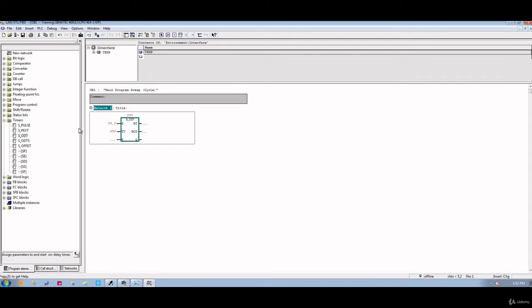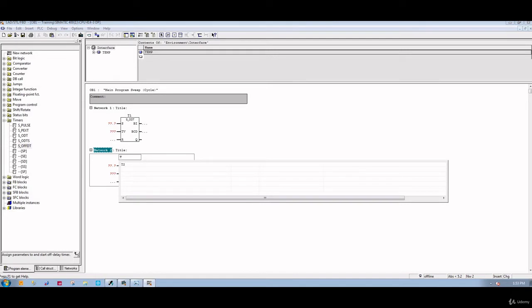We'll try to sample two timers, one called SODT and another one called S_OFFDT. We'll see what's the difference. First, this is the SODT. Let's name that timer. To name a timer, we need to assign a tag name for it. Any tag name for a timer starts with the letter T. So let's name that timer T1, and let's name the other one T2.